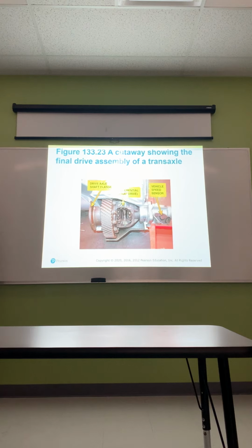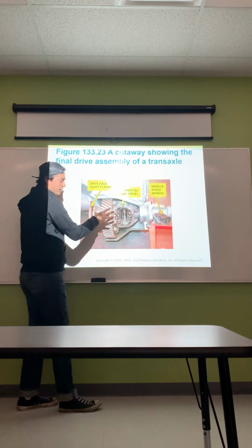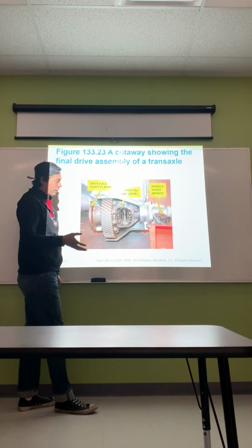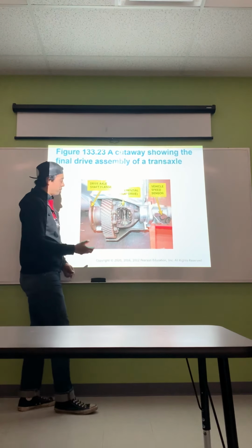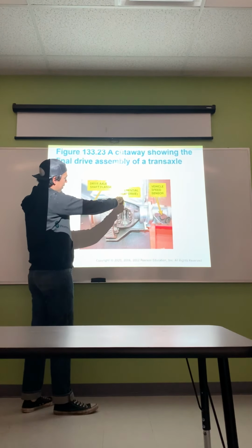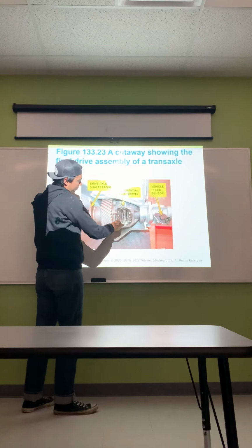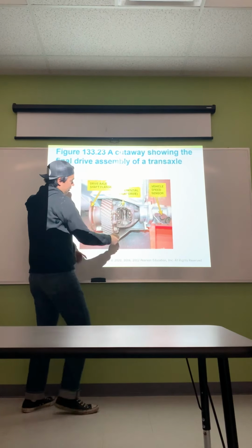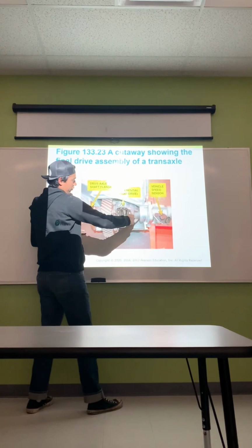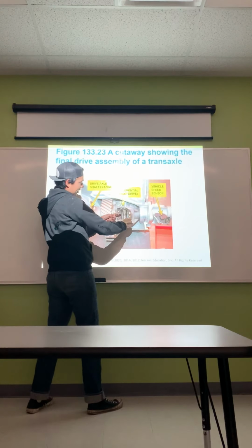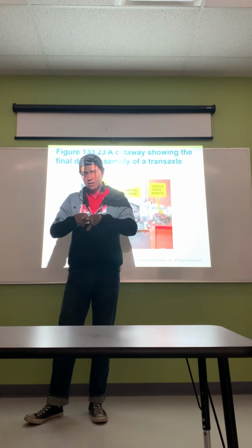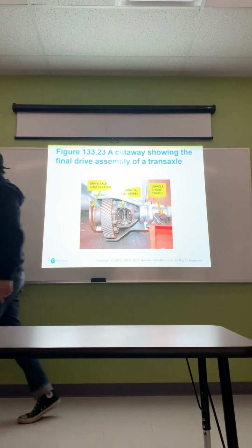A cutaway showing a final drive assembly of the transaxle. Think of this just like the differential that we were talking about in the last module. If you guys are new to the program, don't worry about it. We're still going to go in depth with it. This gear is driven by a pinion gear, which is located in the back. As this gear rotates, you have your spider gears and your side gears. The axles are attached to it. The axle is going to be over here, you can't see it. It comes in and through, which then engages with this side here, which then engages with this side here, which then transfers the energy from the final drive through the axles to the wheels.